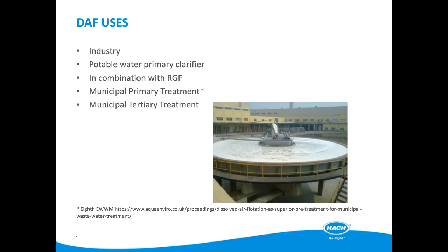For modern drinking water plants, the lower footprint compared to, say, a slow sand filter means the plant capacity can be radically increased, even more so when the DAF plant is formed on top of a rapid gravity filter. An example of this is the COCO DAF, where COCO stands for counter current. Here the separated sludge rises and clarified water flows down through the rapid gravity filter.